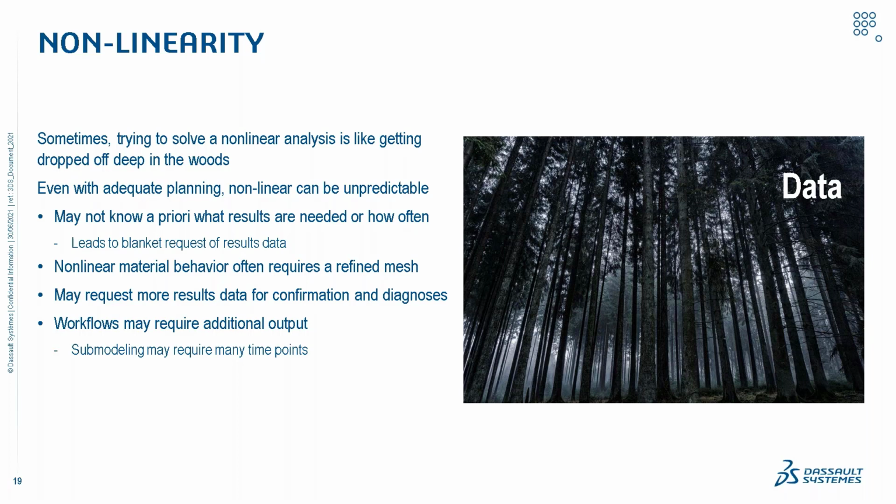You may not know a priori what results are needed or how often, so you may not know exactly how often you need to output the stress or displacement. And this leads to blanket requests of results data. You have nonlinear material behavior that often requires a more refined mesh than a linear material, because you might have plasticity, which is localized to a specific region, and in order to resolve that adequately, you need a refiner mesh.